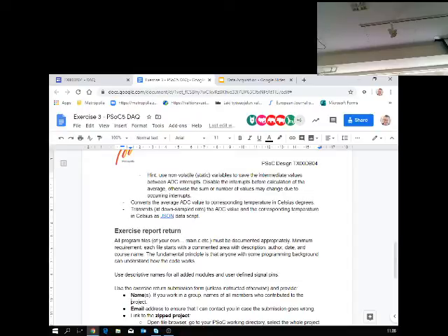So we are expecting something like 230 millivolts at this temperature, or when you put your fingertip on it and warm it, then it would be around 300 millivolts. So those are the signal ranges. But you need to do the calculation so that it basically is a temperature sensor.